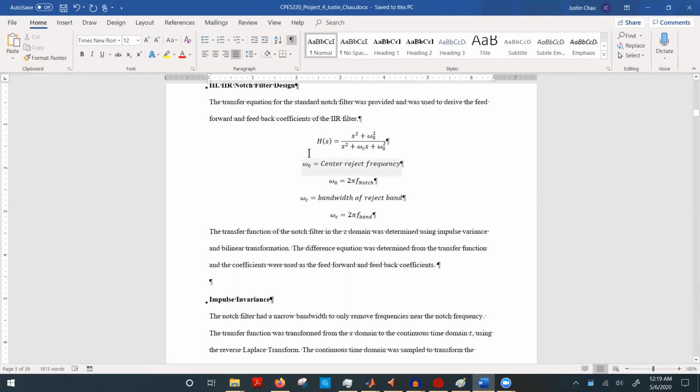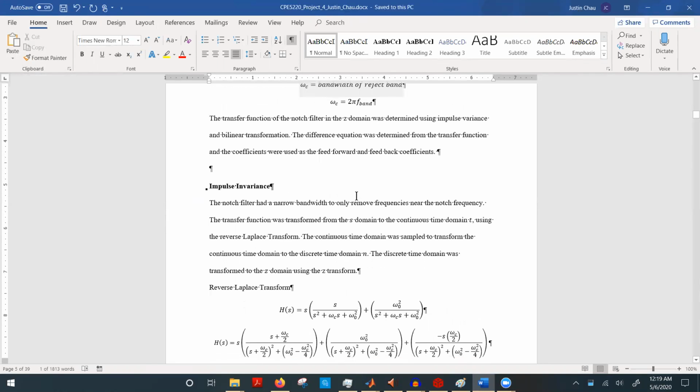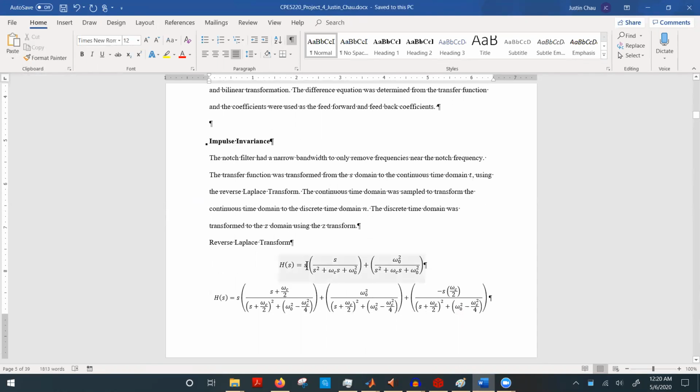The first thing we have to do is transform this using the inverse Laplace transform into the time domain. The first problem we see right off the bat is that the order of the denominator is not greater than the order of the numerator. So we have to do a bit of work. I can factor out an S over here, so that the denominator's order is higher than the numerator. Of course, this S will come into play later because it will count as differentiation,